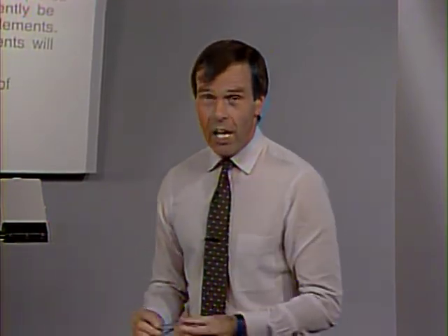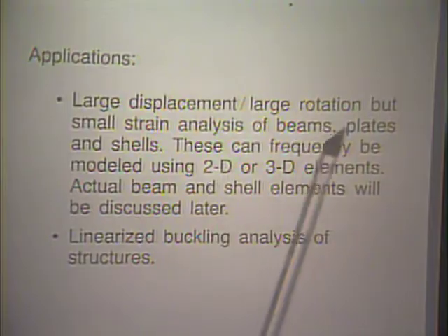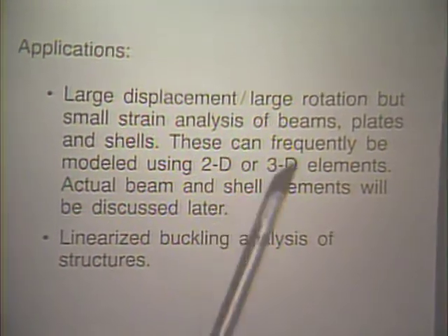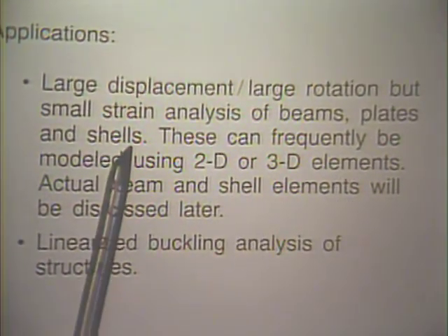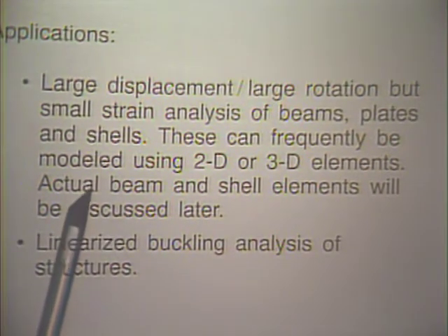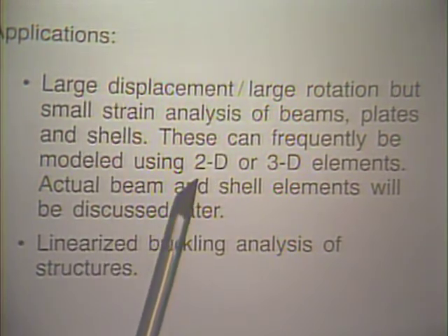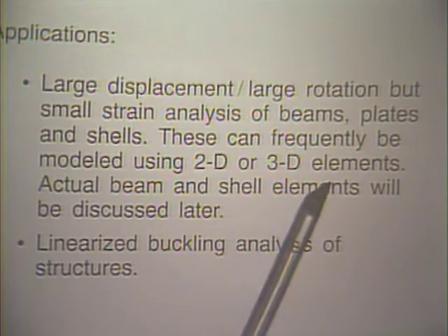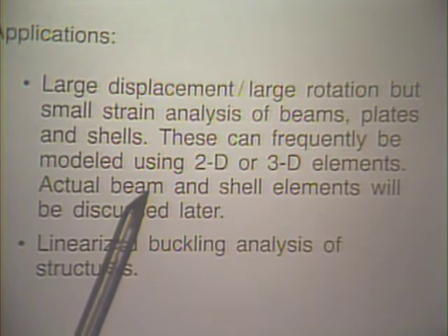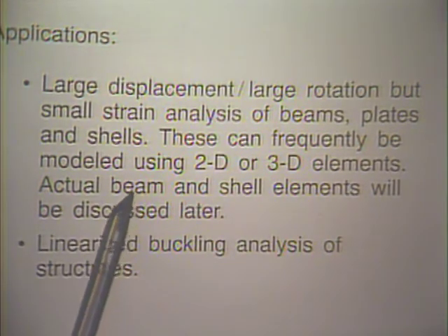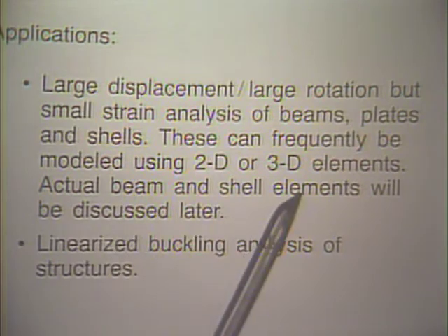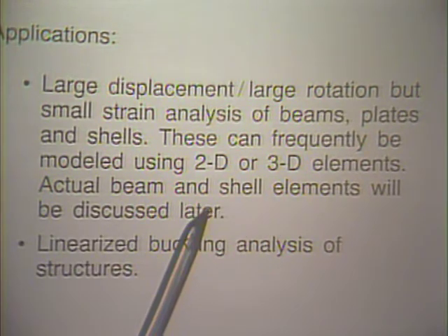Applications are really all large displacement, large rotation, small strain analysis of beams, plates, and shells. We can use for these analyses frequently simply the 2D and 3D elements that we discussed earlier, but we may want to use beam and shell elements, and those we will discuss in later lectures.